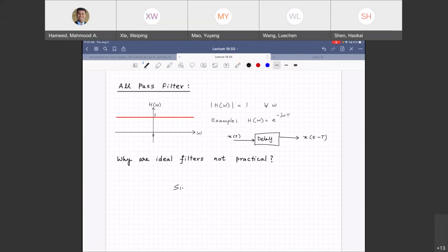So sinc is, what is that? Not time limited. So what you literally do in a communication system is chop off the sinc. You don't take it from negative infinity to infinity. You just take it from, let's say, 3 periods on the right, 3 periods on the left, done. That's your sinc.